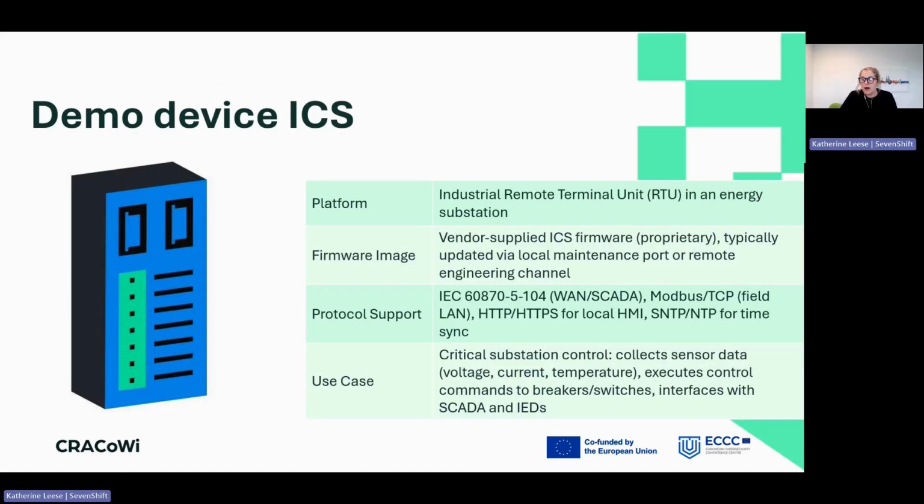For the ICS part of this, we've chosen a random RTU installed in an energy substation. The use of this device is to collect sensor data from other points and to execute control commands to breakers and switches. It has a human machine interface, it talks with the SCADA, and it talks with the IEDs as well.